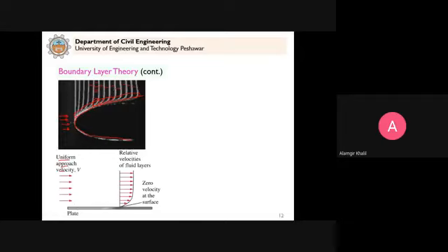But because this fluid flows past this object, you can see here that at this point on the surface, this is known as the zero velocity at the surface, which we call the no slip condition, because the fluid which is in direct contact with the surface will be brought to rest due to the resistance, and then the resistance will be transferred to the other layers, and this results in this velocity profile here, because the resistance will be transferred in this direction.